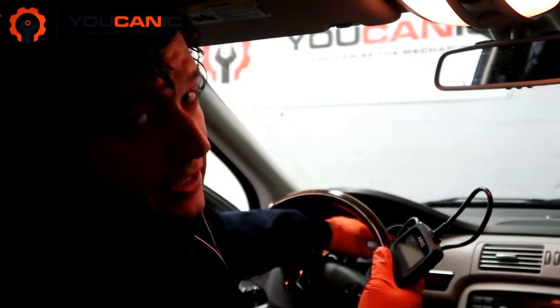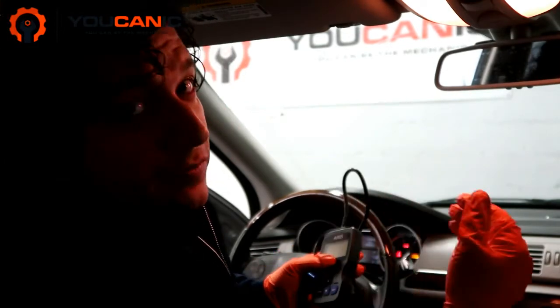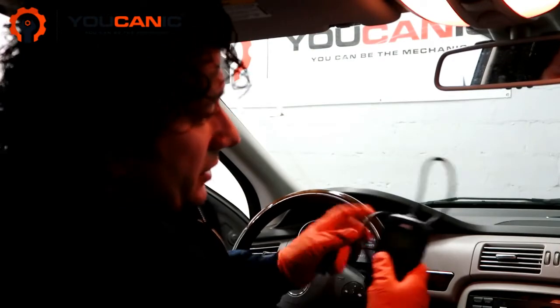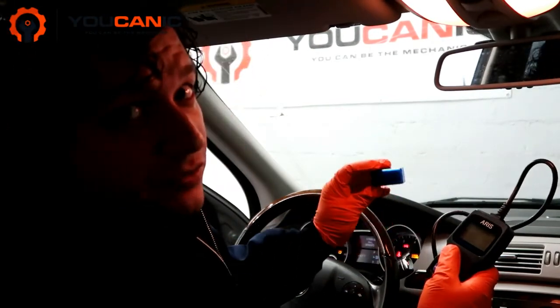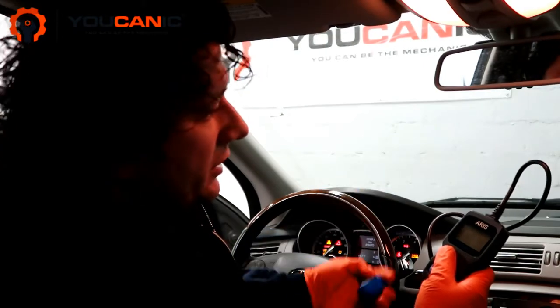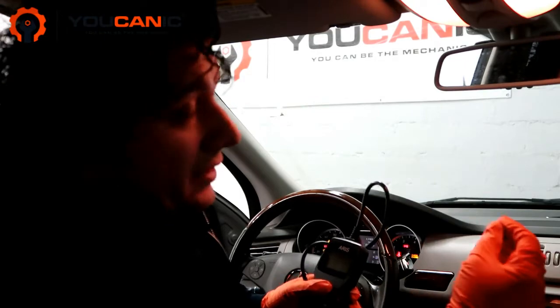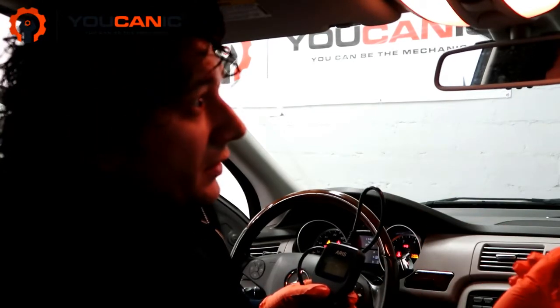But the check engine light also sets a generic code, meaning a code that's required for emission purposes. Those codes are pretty standard, and a generic OBD2 scanner can read them. A Bluetooth adapter sells for like $15, really. They can read your codes, and 9 times out of 10 that generic code will give you enough information as to what's wrong with the car.